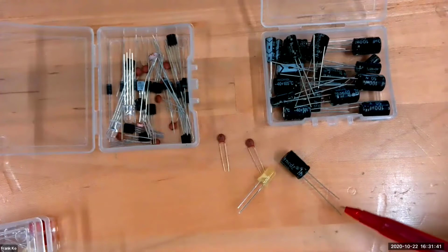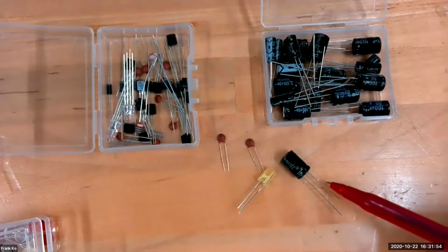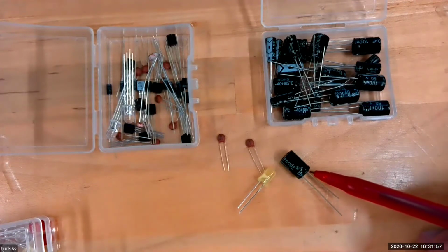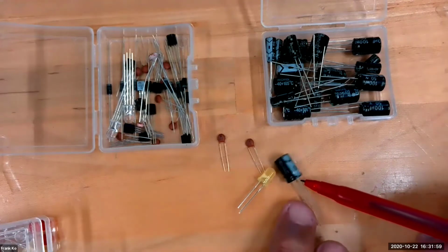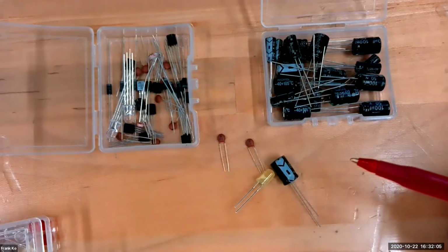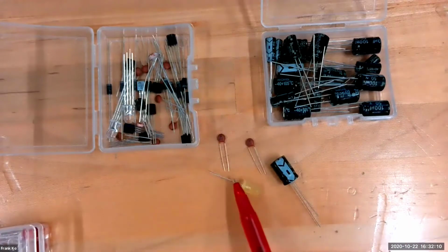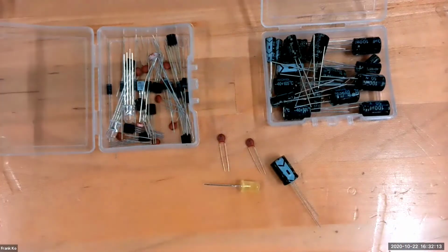If it is polarized, before anybody alters these by cutting them down, as they come from the factory, the shorter lead is intended to be on the negative side of the circuit. And that's why this lead over here is closest to, and if I can spin this guy around a little bit, that white stripe band on the body of the capacitor. Now these guys are relatively small. You can see by the scale of the LED that these are pretty tiny. Now capacitors do come in different sizes and also different shapes. The colors will vary as well.